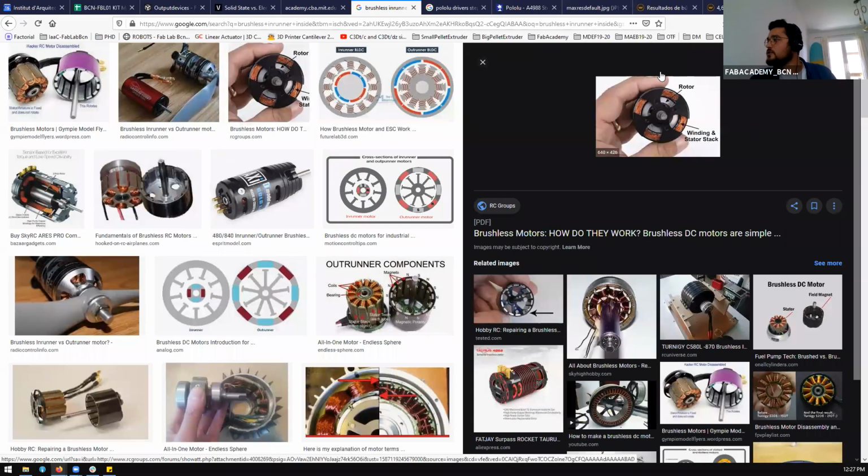Yes. So actually the coils are outside, but the rotating part is inside. Why do we have the opposite configuration? Because by moving less mass closer to the center, we can allow higher speed with proper balance. So the in-runner motors are meant for even higher RPM, but with less torque. This is usually for propellers and turbines to actually make really high rotations.